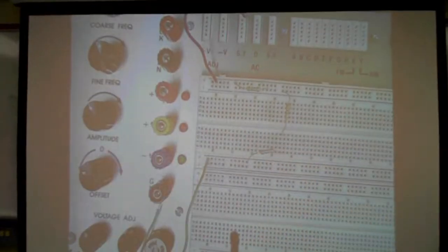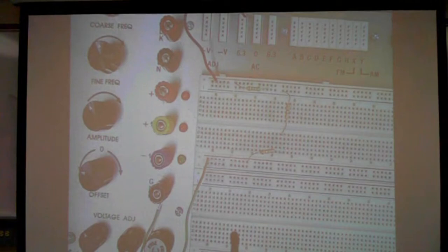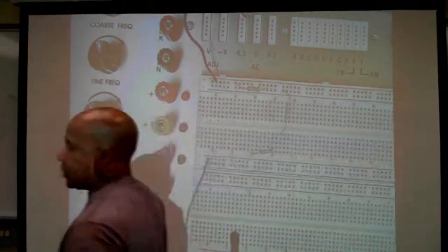You want to make sure your voltage is set for 10 volts. Set the voltage before you connect it up, and then check it again after you connect it up to make sure it didn't change on you. And then that's your circuit connection, your circuit diagram. And then all you're going to do is you'll take your leads. Let me grab some leads.